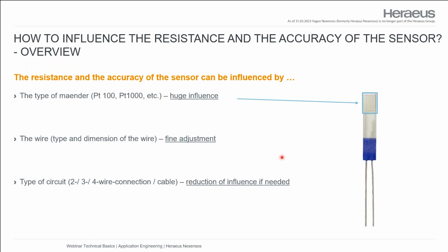Martin, there was a question. Okay, sorry. Yes. Do you believe a norm for NTC sensors will come anytime soon? I don't think so, to be honest. This is only my opinion, but the reason is that with that bulk material, it's hard to describe it in a way that you can exchange it across the different suppliers and manufacturers. That means you always have some variances in the production, and typically if you purchase a very, very good NTC, for example, you get the curve and the characteristics with that delivery. That means the higher the accuracy, the more critical it is to describe it in a good way. This is the reason why I don't believe that there is, at least in the near future, a kind of normation for those NTC types.